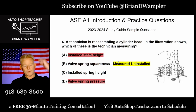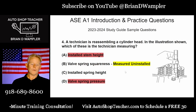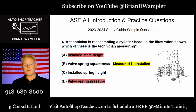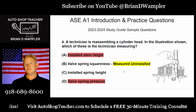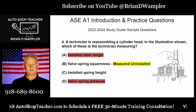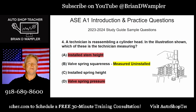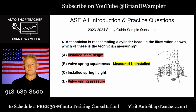Okay, so let's talk about valve spring squareness. And again, this is not a whole course for A1. This is just going through the study guide practice questions for 23-24. Valve spring squareness is measured uninstalled, when you have the spring in a fully relaxed state. It's just its natural state, off the engine. That's when you measure the springs for squareness. That's when they're completely uncoiled, and if there's going to be weirdness, that's when you're going to see it.